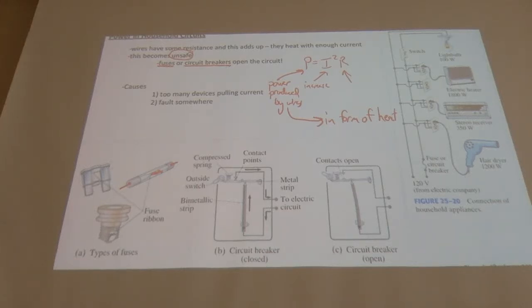So it's trying to keep you safe. So don't get any ridiculously unbright ideas by trying to put in a higher rated circuit breaker or fuse. What you want to do is go look elsewhere. If the thing keeps turning itself off, there's a reason. It's not just like somebody put in 40s instead of 50s. No, the 40s are there for a reason, okay?